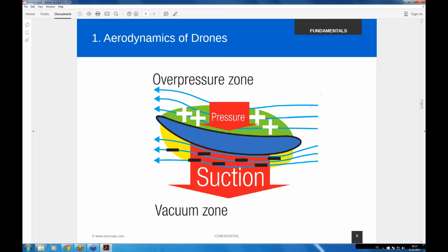The flow is split up here, and if it should meet again here, then the flow on the lower side must be accelerated. For this acceleration you need energy, the same as for any flow, and energy cannot come from nowhere. In this case, the energy needed to accelerate the flow is taken from pressure, so the pressure is reduced.